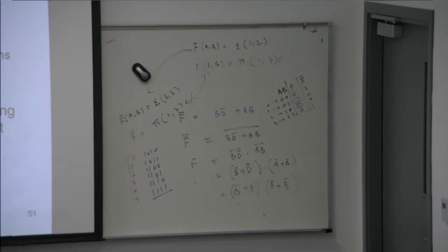So we can give the sum of products expression by selecting groups of minterms corresponding to product terms. And then we can also derive the product of sums expression by selecting groups of maxterms, not minterms. If it's a group of maxterms, are we interested in 0 or 1? Zeros. And corresponding to sum terms, by applying De Morgan's theorem, you can have F bar, and then you apply De Morgan's theorem. And if you have don't cares, they can be marked by X or D. It means that we don't care, and it can be used to simplify the expression.